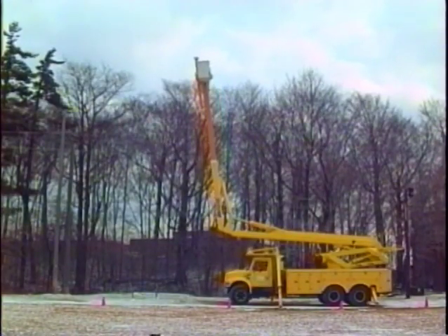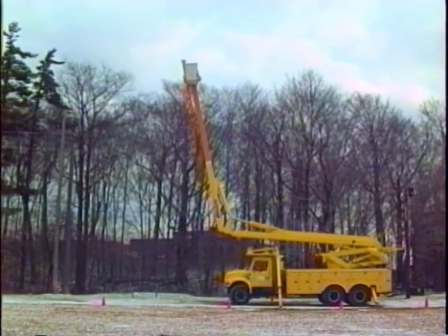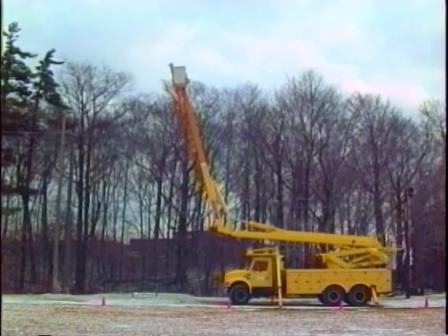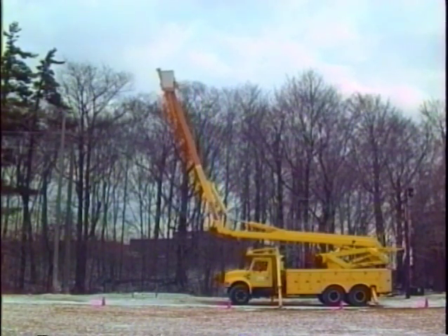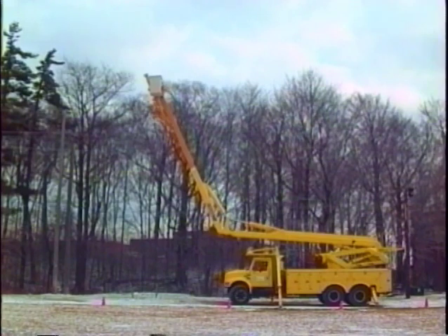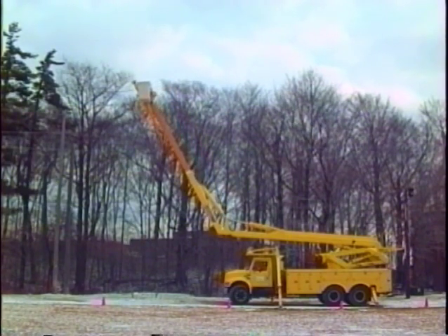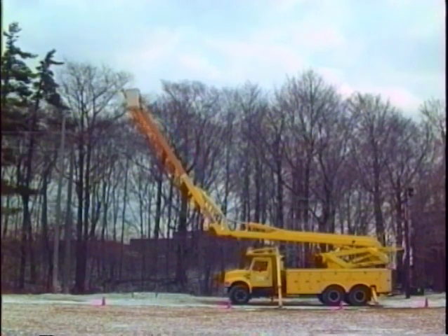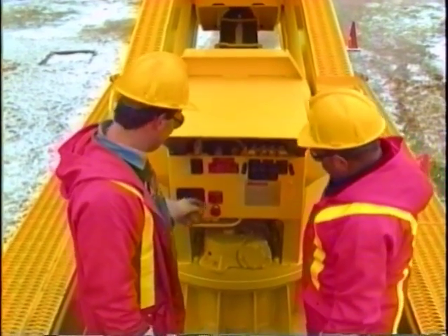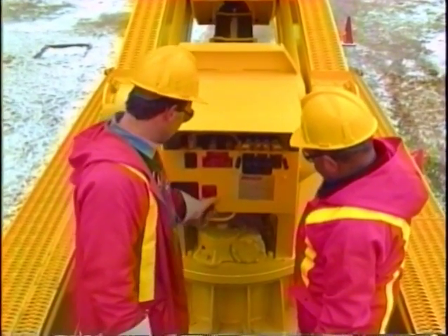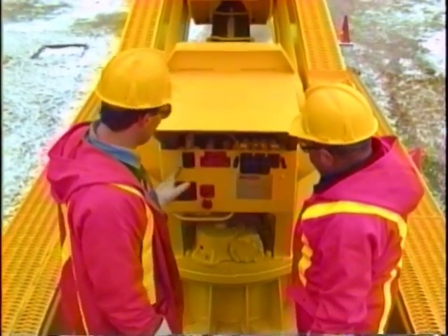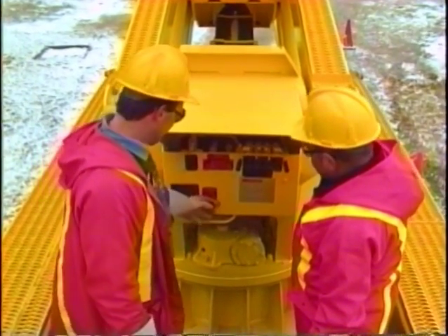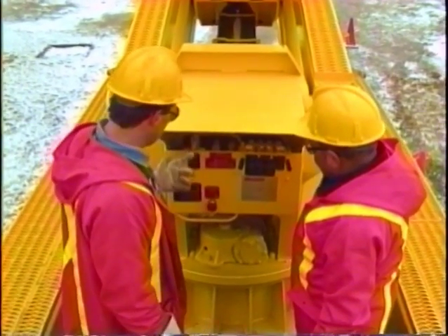If a particular job setup requires you to operate over center, or from a different bucket than normal, take extra care in working the controls. The control directions will be reversed. And still on the subject of controls, make sure that all ground personnel know how to work the lower controls in case of emergency, or in case the upper controls fail.